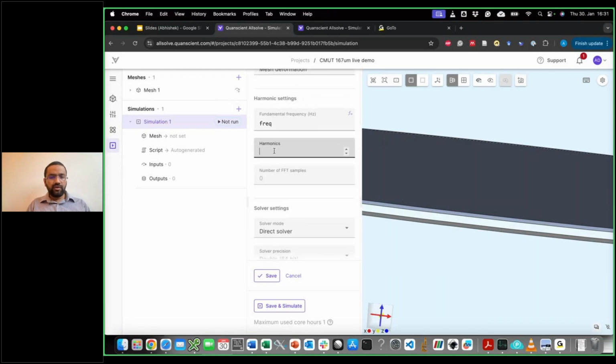Here's where we have to choose the harmonics that we want to represent in this case. So I'll choose the constant harmonic. Then 2 is the sinusoidal coefficient, 3 is the cosinusoidal coefficient for the fundamental frequency. Then we also need twice the fundamental frequency, sine and cosine.